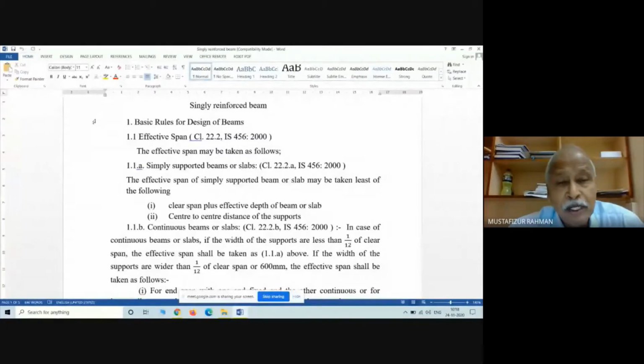Now, all these things we have to assemble together, which is the real structure. So that's why it is the design of beam. Now here you will see, but already you are looking because it is visible for you. We have to obey IS 456, right? Now, when we are to design, what information will be in our hand? In our hand, the information available will be only the span, the length from support to support, if it is a simply supported condition.